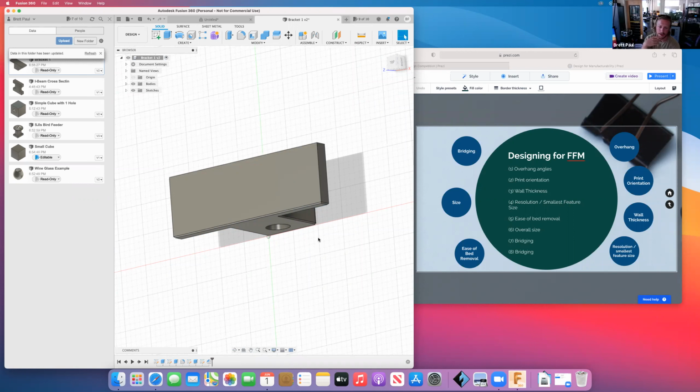That's a great point. I wouldn't necessarily need it on the perimeter for this thing, but if you're printing a 6-inch by 6-inch cube, it's nice to get underneath it from multiple angles and lift it up off the bed. So the answer to that is it depends. But in this case, we'd probably be okay to put it on just maybe this long edge here and this back edge.